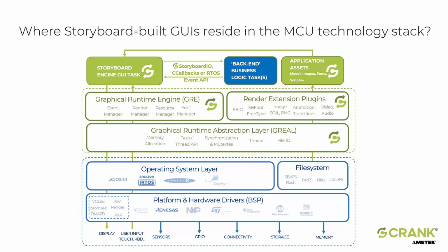So you could, for example, use an RZ V2 or an RZA or an RZE or one of these other platforms, and use the Storyboard engine and the UI prototype to inform your decisions about which platform is the most appropriate. Do you need hardware acceleration, or is software rendering more than adequate? So these sorts of decisions can be done early, and we encourage that as part of the design phase in the specification.